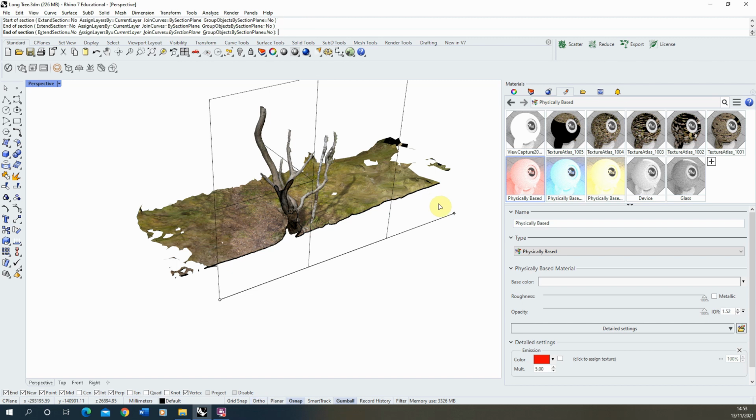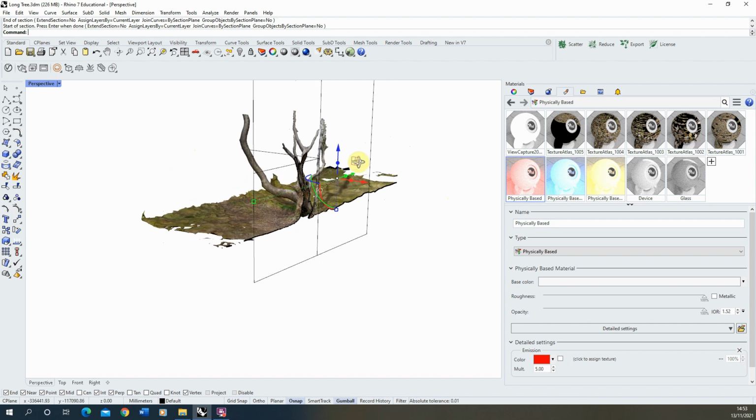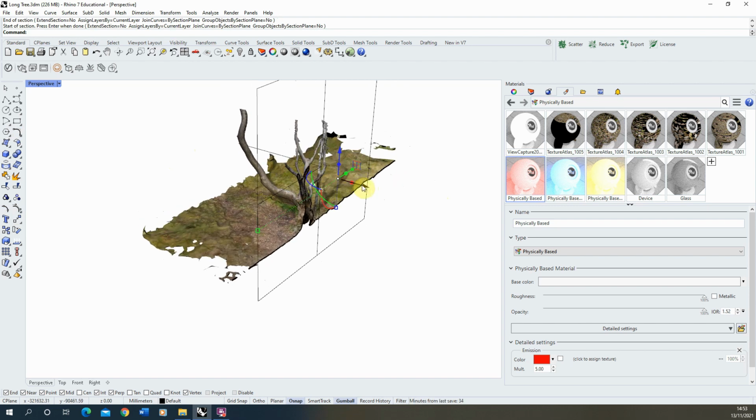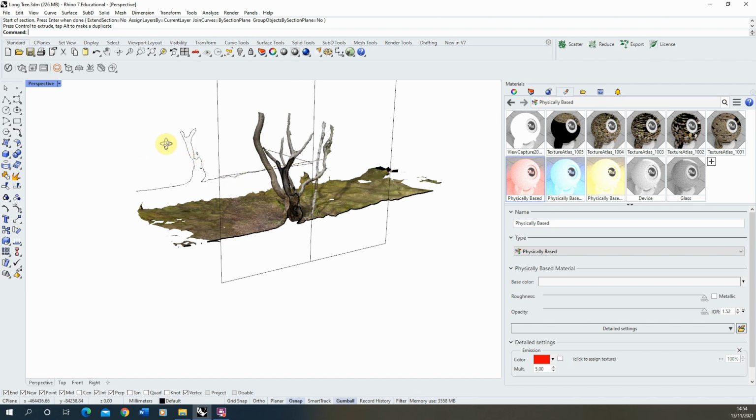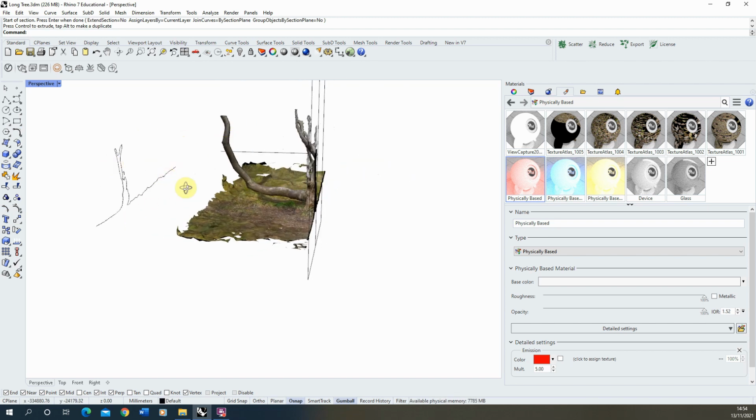And what that will do is cut a section line through the model, and you can see it there. It might be hidden, so we'll just hit escape to get out of that tool, and that section line will be selected, and if we move it, we then get our line here. So there we have a nice section line cut through that model.